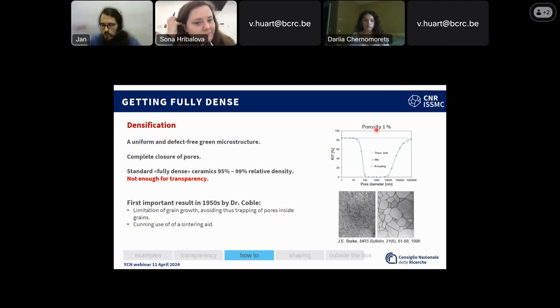Specifically, fluorapatite can be transparent and can actually be a laser host material. And if you prepare it with sufficiently small grains, like the group of Furuse, where you can see, or at least I hope you can, some maybe 100 nanometers grain size, again, the scattering is not that strong, and they were able to get quite nice transparency here. But for this specific material, this is not the only possibility of how you can get it transparent. And the other one is even fancier.